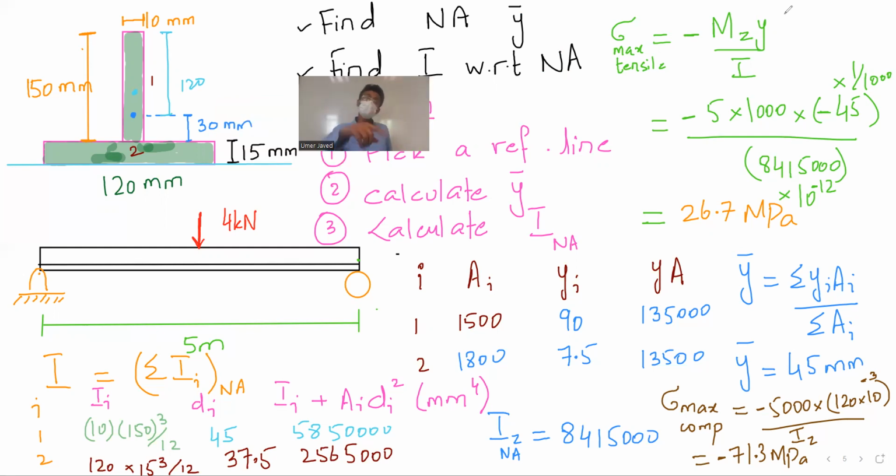Yeah. So for example, if you're putting the load from the top, the load is acting here. How will this object behave? The object will bend like this, right? If the object bends like this, which is the fiber that will have zero stress? That will be the fiber that goes right through the neutral axis, that is the centroidal line.